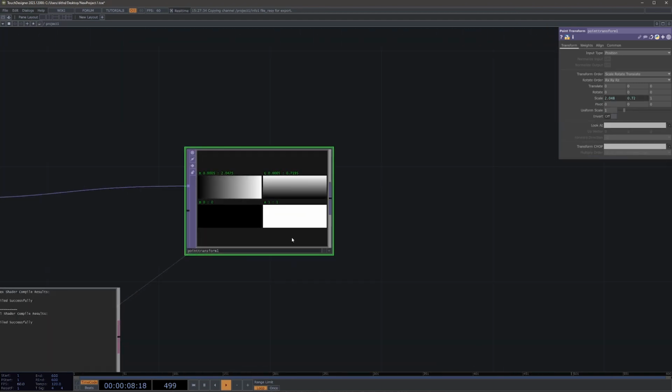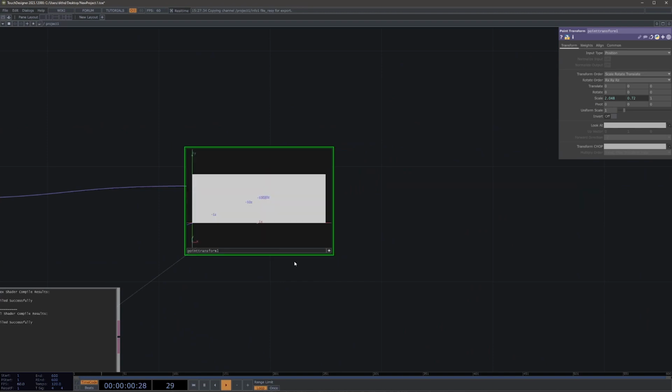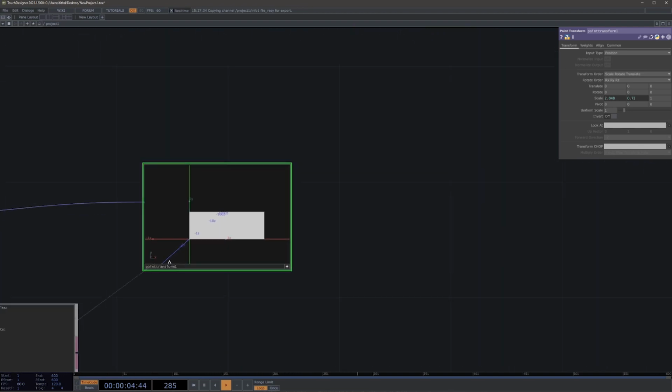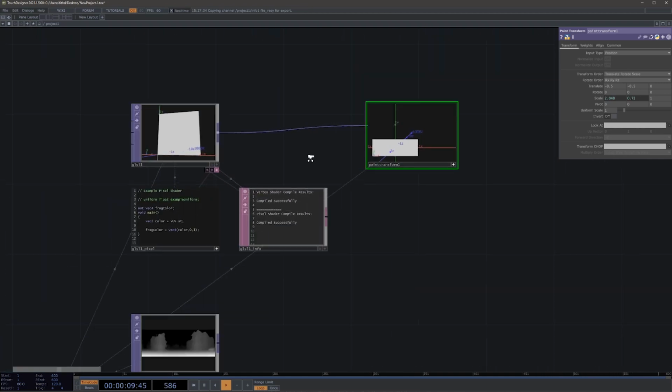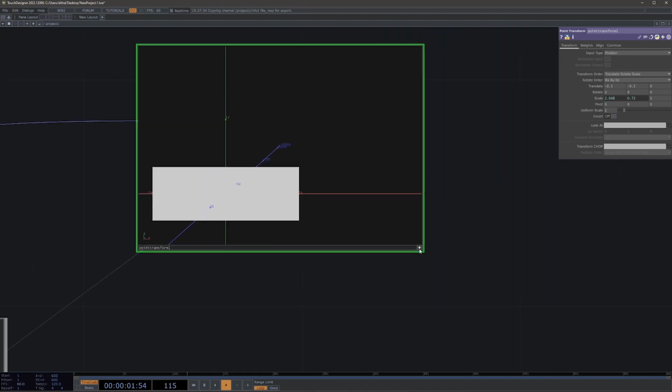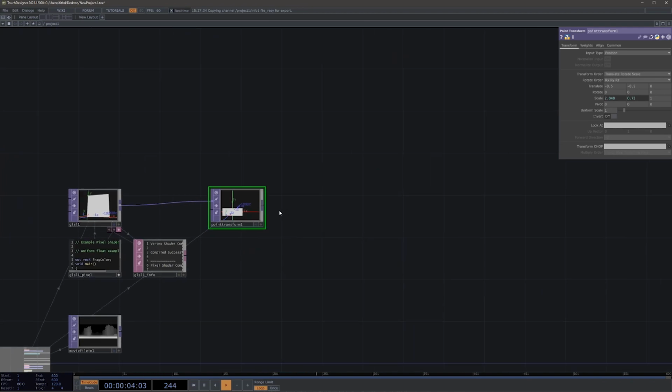Now we should have a grid which fits the ratio of our pictures, but we want it centered. So let's translate it by -0.5 and -0.5, and we want to offset it before we do the scaling. So here let's translate, rotate, and then scale. Now we have a grid which looks like what we want, and we will need to instance it.